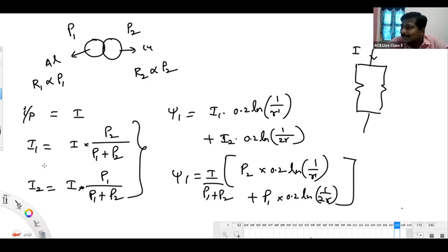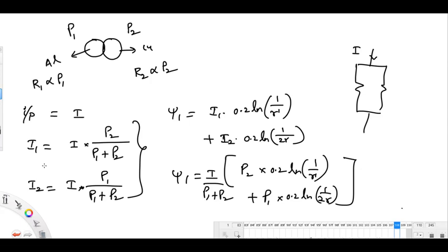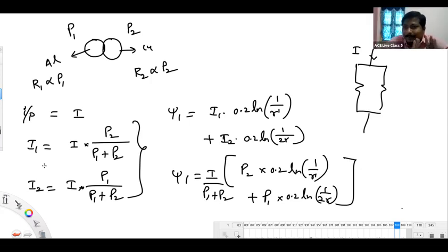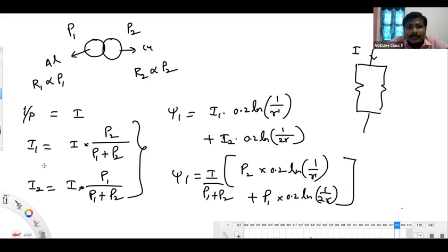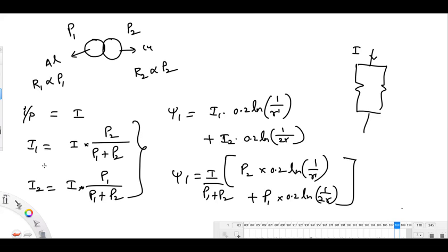Flowing in the line, then what is the disadvantage? We have inductor and capacitor, we cannot neglect that. Your statement is perfect. It's flowing in the line, then what? On account of that, there is some excess current flow in the line. Then there is more voltage drop in the line, causing a fall in the receiving end voltage. That's the problem of reactive power. Energy wise, I don't have an issue, but voltage drop wise, I have an issue with reactive power.